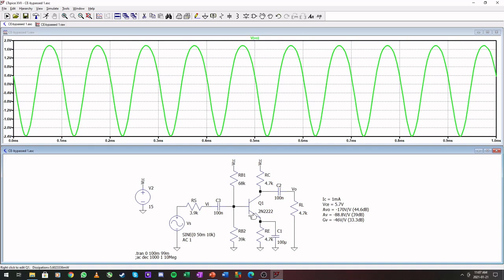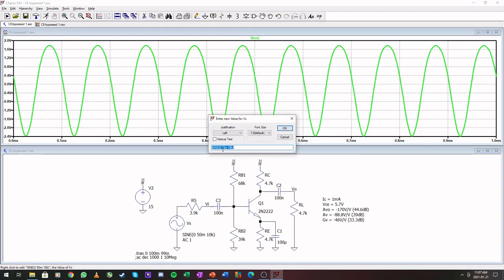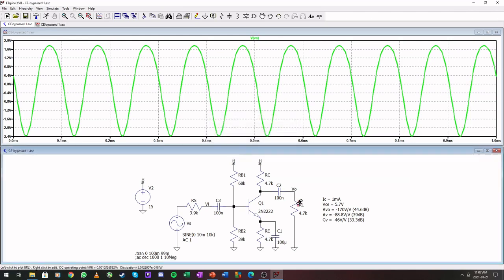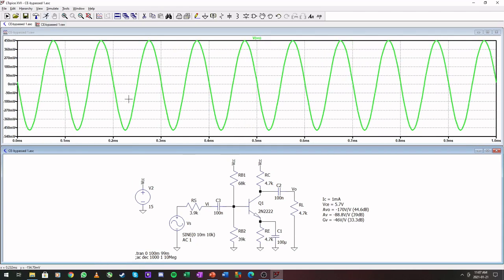So there's only a small portion where it's considered to be linear, and that is the plus minus 10 millivolts around VBE. Right. So always try to keep this input small, except if there is an extra unbypassed emitter resistor, then this won't be a problem. Okay, for the AC analysis, you can use 1 volt, then you don't have to do any